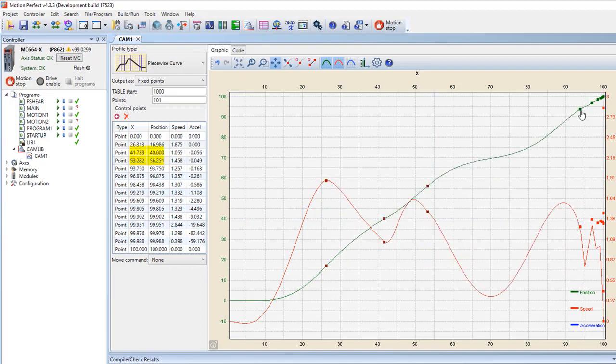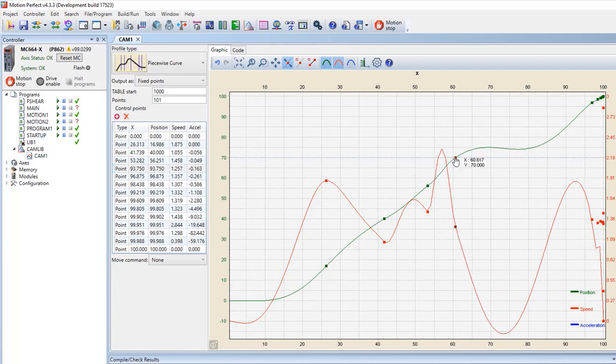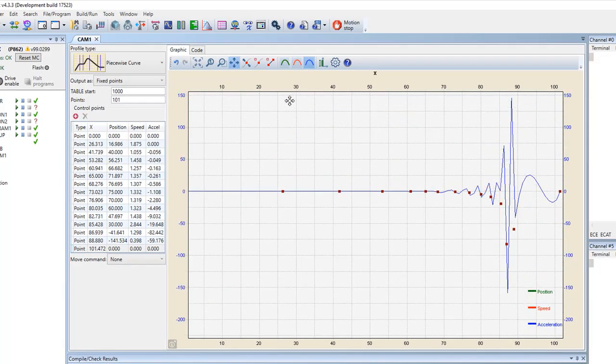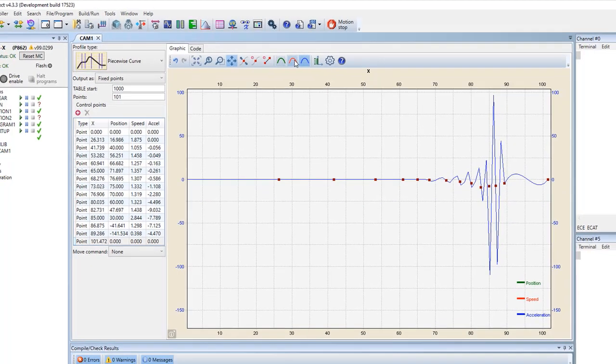The position points, and you can see the speed value is kind of wanging up and down. So to get it smooth, you'd have to try and make it so the speed transitions were relatively smooth as well. That's the acceleration. So that's your acceleration curve at the moment. And again, you can try and play with that to minimise some of those, if that's possible to do. It is calculating some kind of spline interpolation to do this. Goodness knows what that's done to the position curve now.